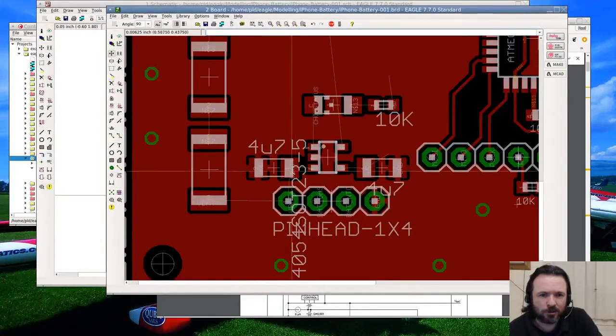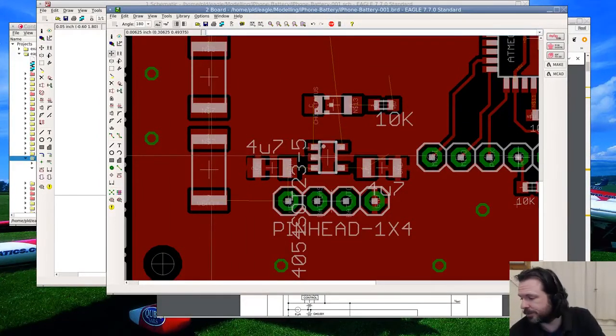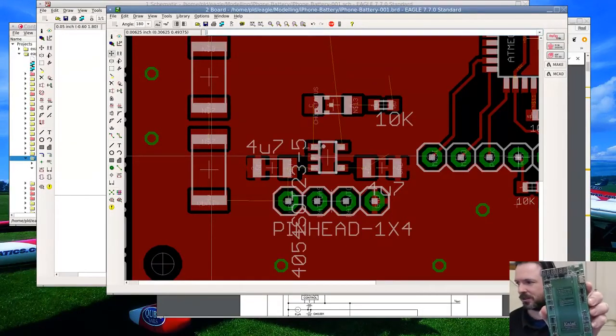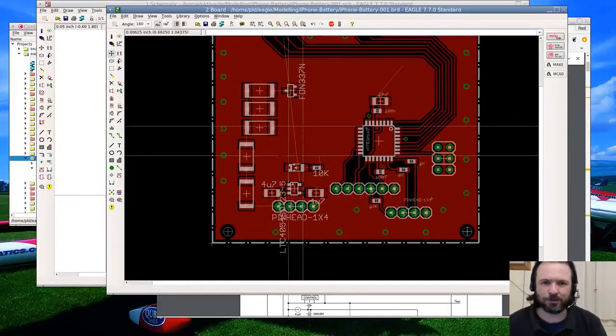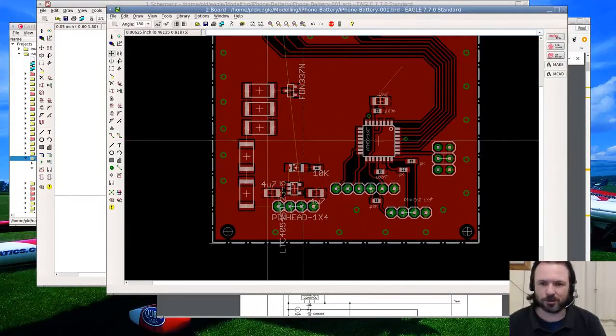Now here's the question I've got in the back of my head. Who am I going to get to do the daughter boards? Because basically what I want... Yeah, unplug this. I'm going to want someone to produce some sort of compact version of this, which simply has all the different connectors on it, and then a 4-pin header. Because I don't mind perhaps manufacturing the board that I'm currently doing, but these phone connectors, the battery connectors, they just look like a nightmare. I mean, and that's with reflow, because I will be doing this using a reflow oven.